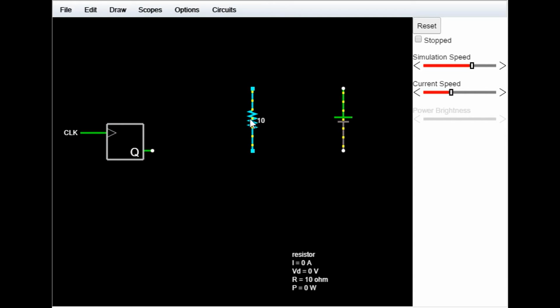So this is like a representation of a microcontroller. All right, here's our motor. A resistor is a pretty good approximation for a motor when you're driving the motor at top speed. It's not a perfect representation because the resistance within a motor changes based on the load that the motor is lifting. So if you're lifting a very heavy load, in other words, if the motor is being stalled, the resistance actually goes down, and it will start consuming more power.